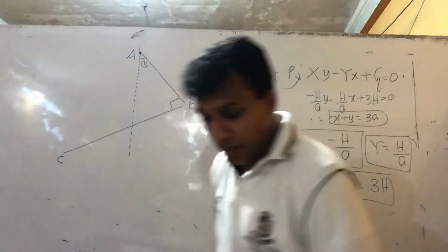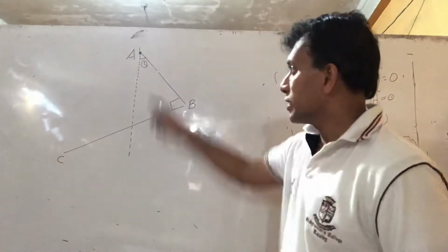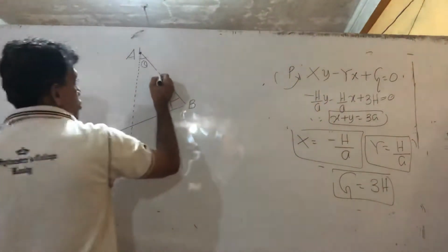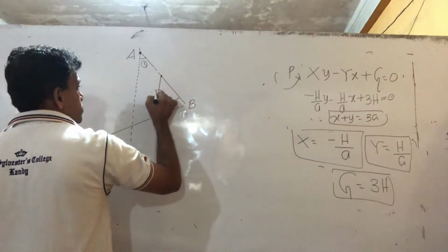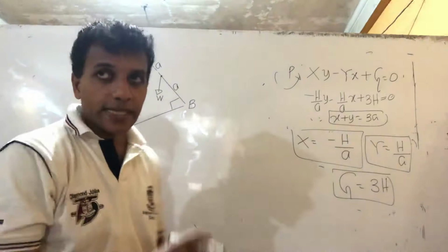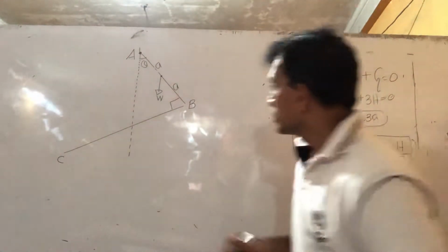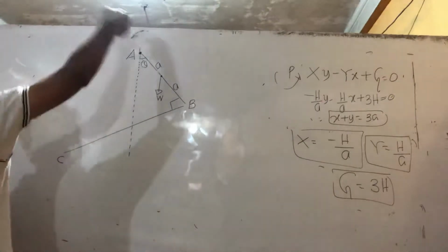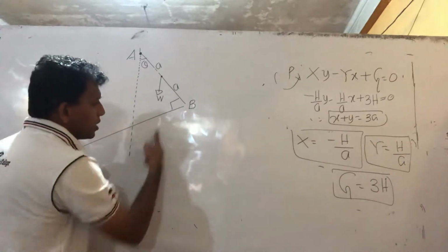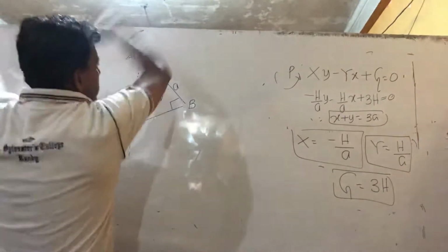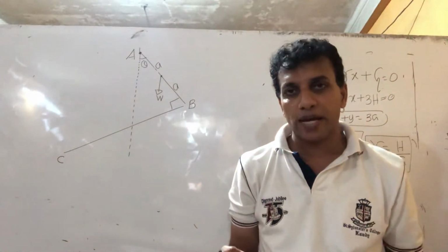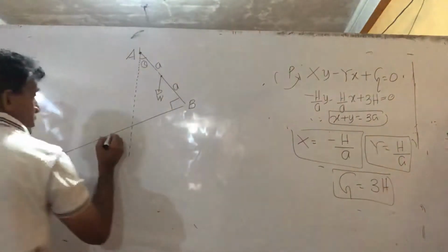They said AB and BC are 2 equal rods. That means the weights are equal and the lengths of the rods are also equal. If I show the force diagram, W, I take as a, right? Here 2a is the length of the rod. There is 1a, 1a. If I take the moments about this, with W on this side, the other W should be on this side. That is the actual diagram. If you mark the W both on the same side, it turns completely and the equilibrium collapses. You can't get a proper static diagram. Therefore the second W you mark somewhere here.